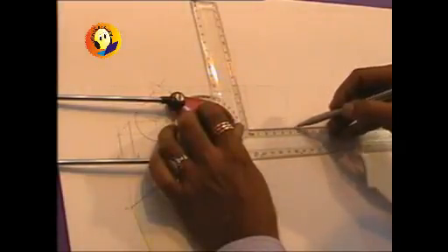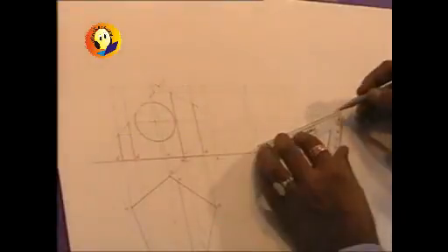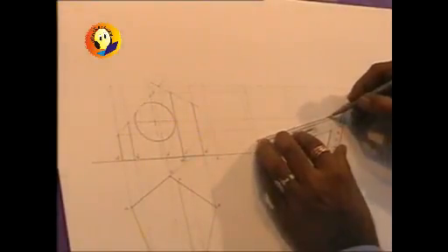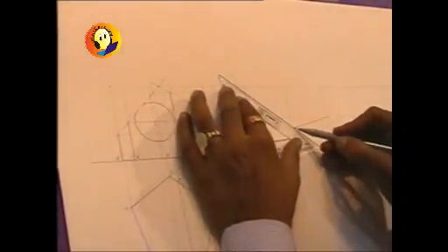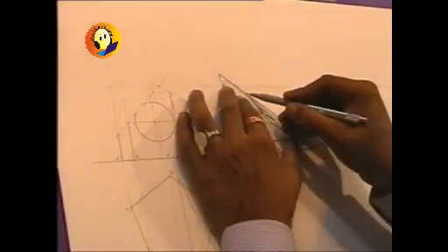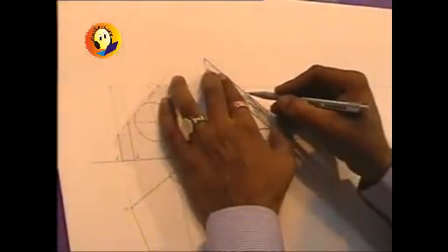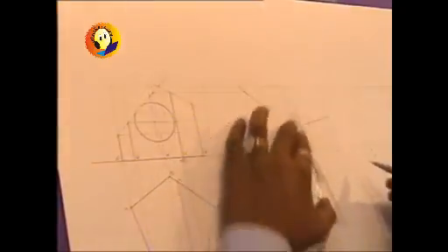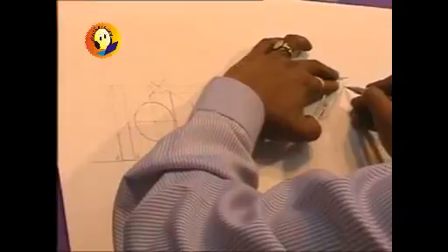So these points can be marked, and the first cutting plane will be shown in the section form as from generator A to point on generator B, from generator A to point on generator E, from E to point 2, and from point on generator B to point 1 of the top.